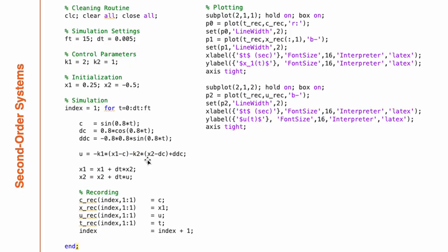But now the question is, what happens if C dot and C dot dot are not available? For example, I gave this example if you watched the first order systems video. Sorry for the repetition, but I think it is necessary. Let's say I am a pilot and I am generating C. It is not pre-recorded. Let's say I am flying and there is a tree. I need to go left and right, so I need to go on the fly. This is a real-time command. Let's say my joystick is measuring which commands I am applying. And let's say you have measurement noise.